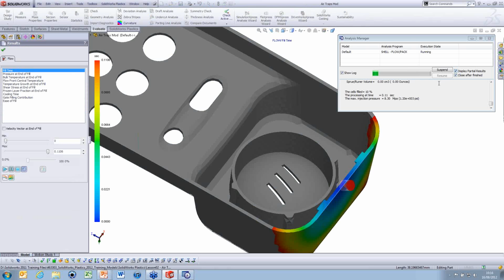So we can see we get running information in terms of the injection pressure required to fill the mould, so the amount of pressure that's forcing the plastic in, which can be quite useful. You don't want an overly high pressure. But we can see straight away here that the flow front is actually remaining reasonably constant through that boss now.